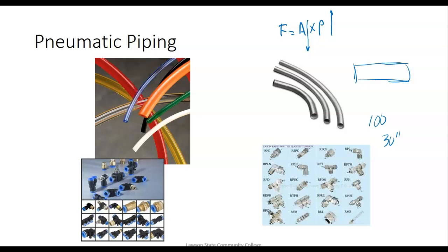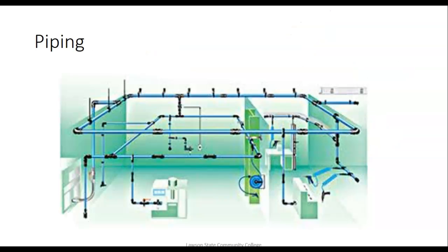The problem we have with air is it's constantly trying to decompress. So we can control the speed, but we can't control it precisely, and it's jerky because every time the cylinder moves, it tries to uncompress. So that's the big disadvantage of pneumatics. We also can't run gases at extremely high pressures, because the higher the pressure, it's going to turn into a liquid.